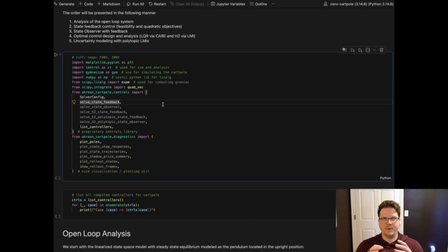It's just basically getting the dimensions of the state space matrix correctly, if I'm doing the state feedback. Once we get to H2 and further, like H infinity, which won't be in this tutorial series, you want to have more port allocations, like where the disturbance channels enter the plant versus the control inputs, and likewise performance outputs versus nominal output.